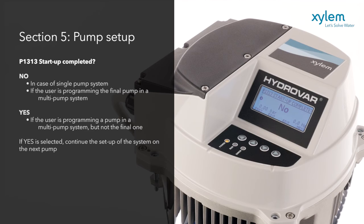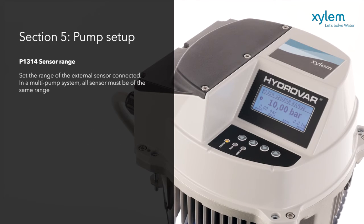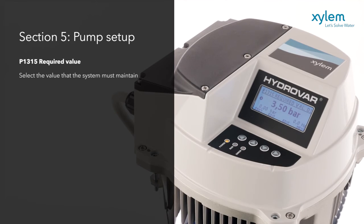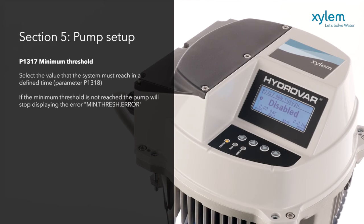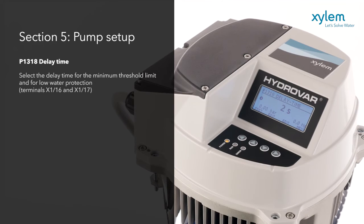A range of further settings are now available directly from the panel. Select and calibrate the sensor prior to the system going live. Set the required pressure in the system. Choose the starting point for when pressure drops and the minimum threshold for the pump to turn off when pressure or flow does not make duty within a set time. Similarly, delay times and water protection thresholds can be set.